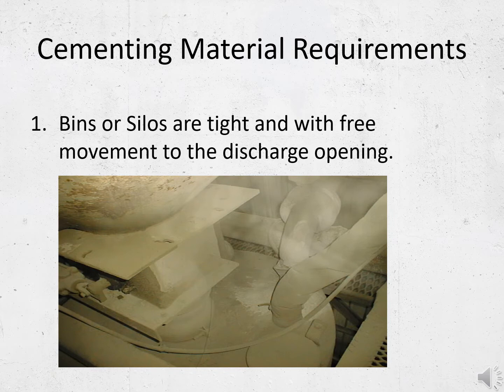All cementing material silos should be inspected for tightness and free movement at the discharge opening to ensure that no materials get hung up in the system and that no materials are exposed to any contaminants or sources of moisture that could prehydrate or degrade them in any way.